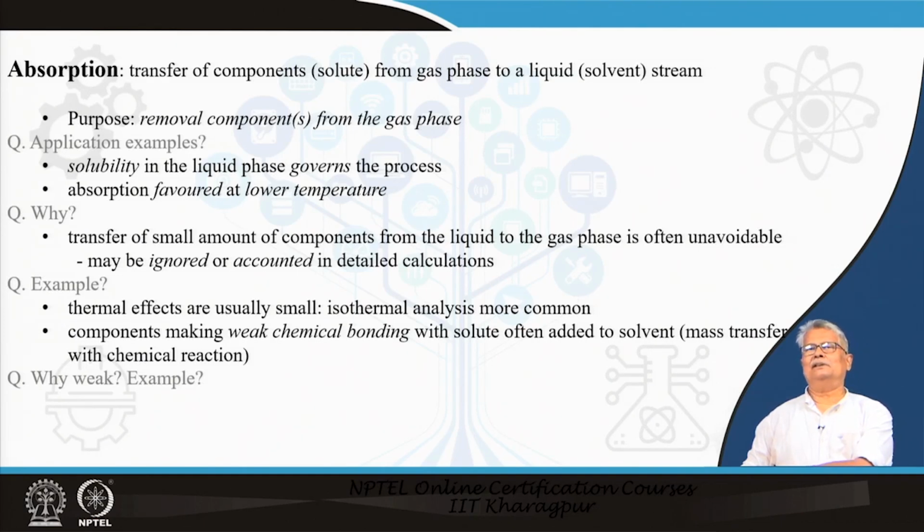Well, there is a limit of physical solubility of the ammonia. In fact, it is not exactly physical, but there is a limit of solubility of ammonia in water. But if I want my solvent, which is water, to have even higher capacity, what we could do is add a small quantity of mineral acid, could be HCl, which would react with the ammonia, which gets dissolved and dissociates as ammonium ion, and definitely removes the ammonium ion from the system.